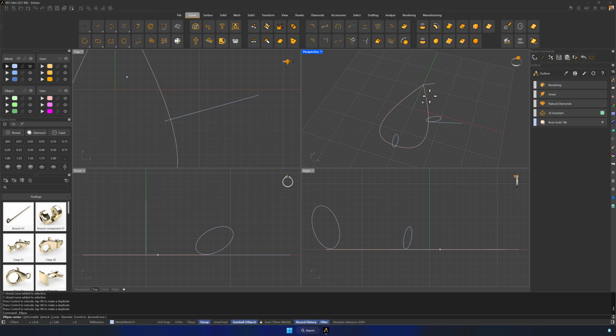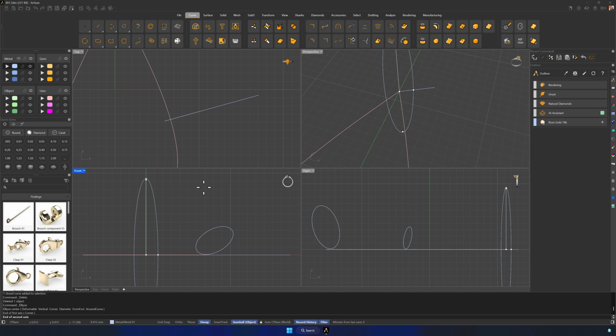Select the starting point, type 3.2, divide it by 2, and then use the perpendicular line to define the second point. Then, from the front view, type 2.2 and divide it by 2. Now we have our third ellipse. Rotate it using the gumball, holding Shift to ensure it rotates 90 degrees. Then position it above the horizontal axis and to the right of the vertical axis.